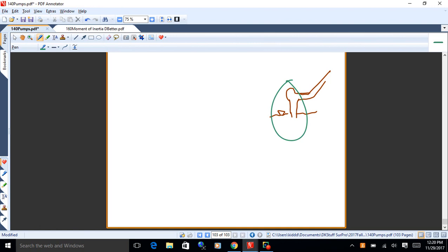So what you do is you take your atmospheric pressure, and generally speaking, atmospheric pressure is what? It's 14.7, but we're going to convert it into feet. Generally speaking, we get everything in feet so it matches. So it's 34 feet. Okay, that's what you start with. That's your energy right there. And what's happening with your pump is you're creating a vacuum in the volute, so the atmospheric pressure pushes the water up the pipe, up the inlet pipe.